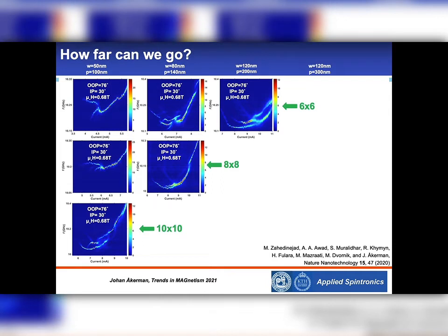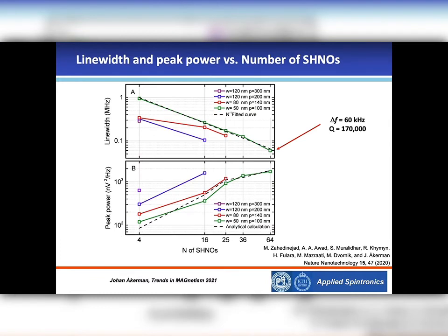And we can summarize these signal properties a bit more by looking at their line width and power. So we picked the best line width and the best power from such measurements, and we show them in the next slide. So here we can see that the line width is improving tremendously with n, where n is the number of synchronized oscillators. But I plotted this on a log-log scale because the dependence is exactly inversely proportional to n, which theory also predicts. So the green data are for the smallest constrictions, which are closest together, and you can see that they follow a 1 over n dependence all the way up to 64 oscillators.